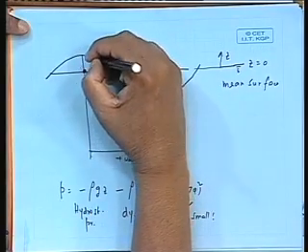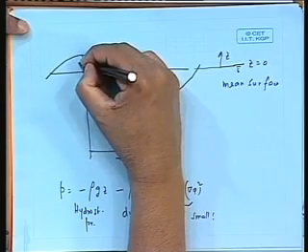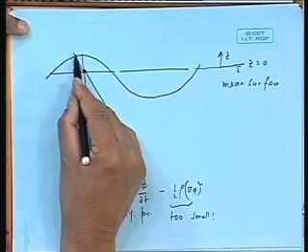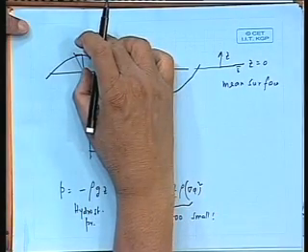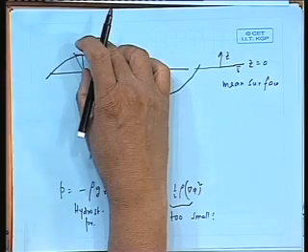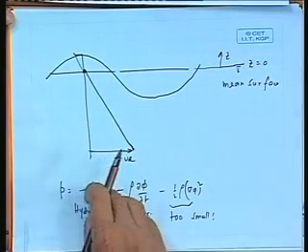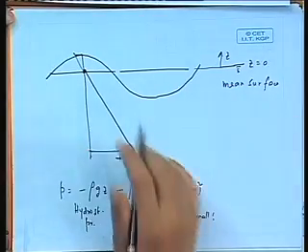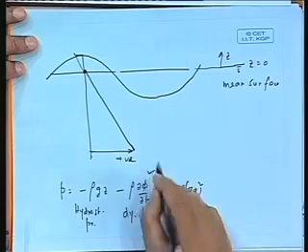What about up? Now, here comes the contradiction. Supposing I want to take in this region the pressure, the hydrostatic pressure will look like that. What is this meaning? Supposing I take at the height, say this wave height is 2 meter, it will tell me that the hydrostatic pressure is negative. That does not make any sense, right? If I use this formula, Z is a positive value, so minus rho g into plus 1 equals minus some kilonewton per square meter of pressure. Now, what is the meaning of negative pressure? Negative pressure does not make any sense, but let us look at this curve.